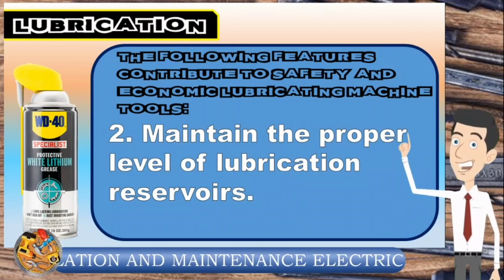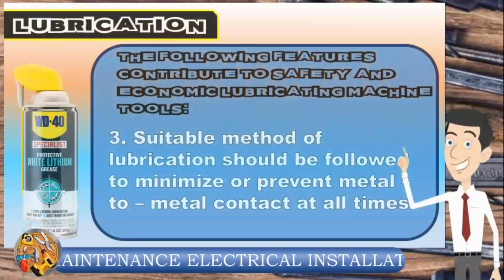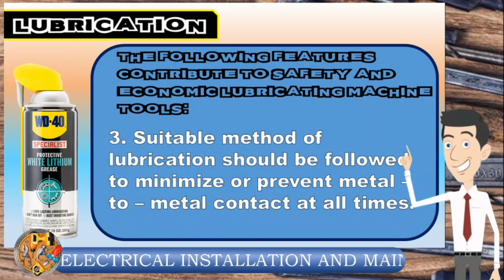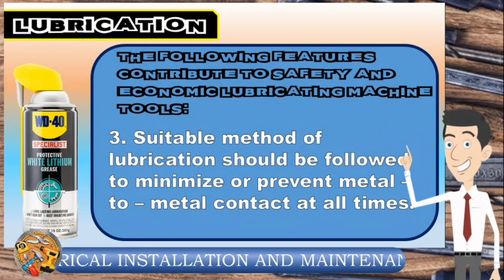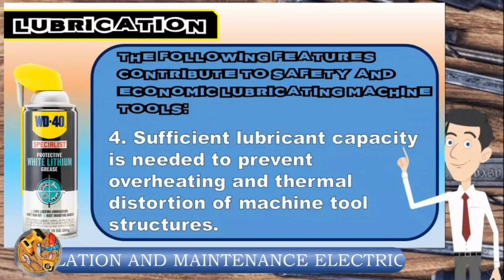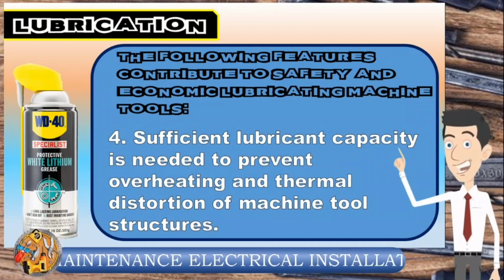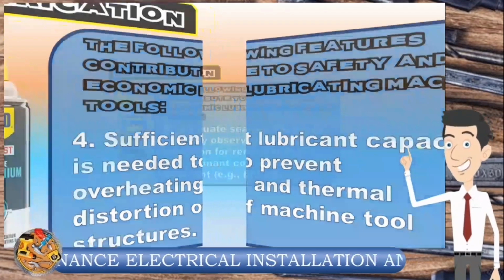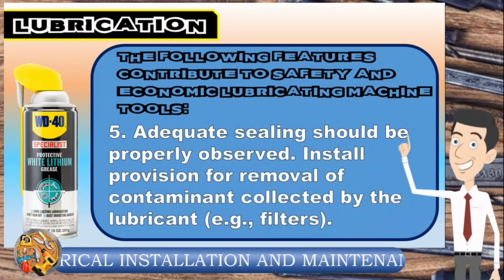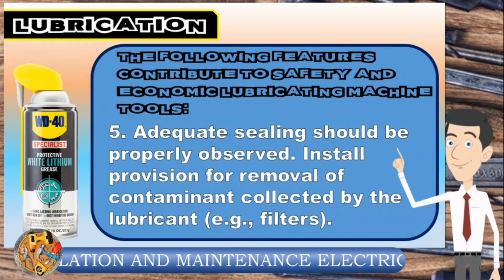We have number 2. Maintain the proper level of lubrication reservoir. And number 3. Suitable method of lubrication should be followed to minimize or prevent metal-to-metal contact at all times. And we have number 4. Sufficient lubricant capacity is needed to prevent overheating and thermal distortion of the machine tool structure. And last, adequate sealing should be properly observed. Install provision for removal of contaminant collected by the lubricant.